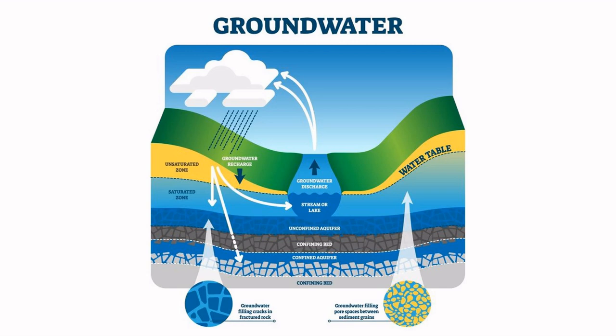So the moisture fluctuations caused by the plants generally diminish until a depth of 30 feet is reached. The moisture in the upper few inches of the soil also changes owing to large fluctuations of temperature and vapor pressure induced by variations in the air and the groundwater temperatures.